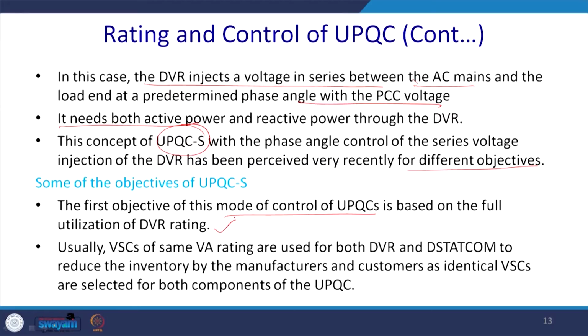So, the first objective is to utilize the proper rating of these devices. The mode of control of UPQC is based on full utilization of the DVR rating. The DVR rating has to be fully utilized, and only then do you load the current handling capability of this D-STATCOM.